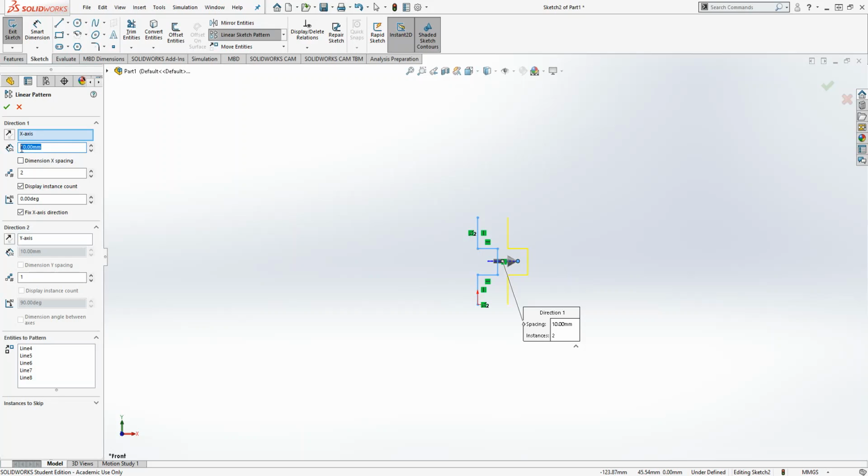Or maybe some sort of part that fits in, slots into an X part, right? So now what I have right now is I have these just multiple different lines that I've set up. It's very possible that I want to use something called a linear sketch pattern, right, to create this pattern of lines that you see here over and over again and move it somewhere else.